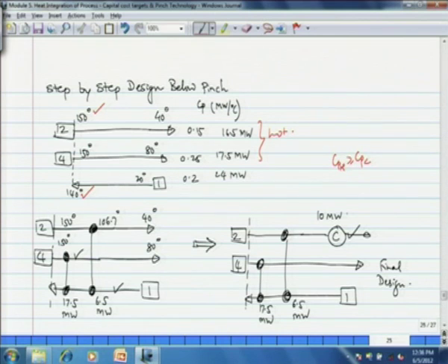And then again we have to see which heat duty is lower. Stream 4 has 17.5 megawatt available with it and stream 1 requires 24 megawatt. So, all of the heat of stream 4 can be absorbed in stream 1. So, now stream 4 is ticked off, it meets its target temperature of 80 degrees, but stream 1 still requires 6.5 megawatt of heat.